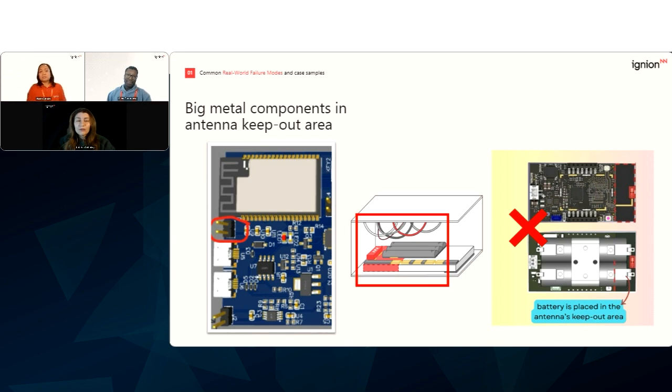Yeah, of course. So if you change anything, especially the size of the PCB or antenna placement, like you want to turn it or put, for example here, a battery close to the antenna, that must be tested. Ideally in the simulation. So if you simulated before in some full wave simulator, ideally, or if you have your prototype, you can test that in the lab, also can do. But just assume that it will work? Probably it will not work as you think. And Sifiso?